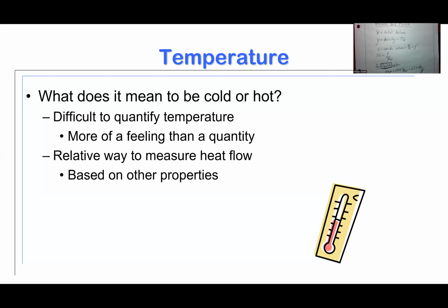We can also use those ray gun looking things that you point at an object and pull a trigger, and it basically measures the black body radiation, the infrared emissions. It's literally measuring other properties to determine the temperature. We can also use voltage change between two metals.